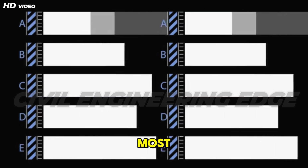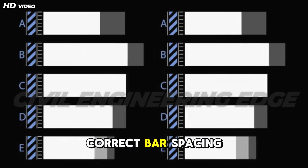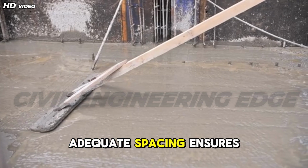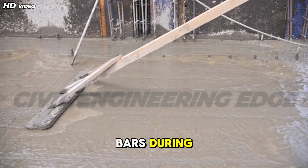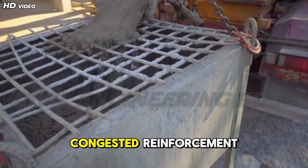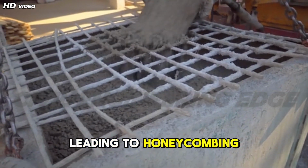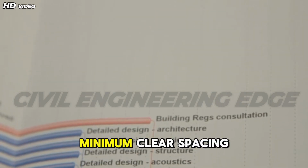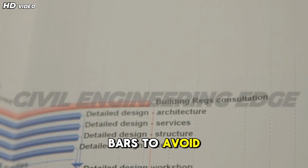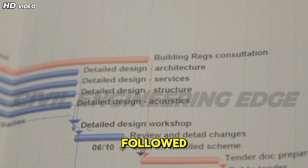One of the most important aspects of reinforcement detailing is maintaining correct bar spacing. Adequate spacing ensures that concrete can flow easily around the bars during placement and compaction. Congested reinforcement restricts concrete flow, leading to honeycombing and weak zones. Codes specify minimum clear spacing between bars to avoid such issues, and these requirements must be strictly followed.